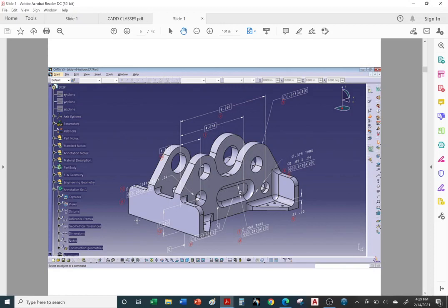The thickness of a credit card or an ID is roughly about 0.020 inches. So you're pretty much telling the machinist and the inspector it can be off by a thickness of a credit card in either direction, on the heavy side or the light side. Okay, so I would have to create a 2D drawing of a front view, top view, side views, and any additional views, and throw in the dimensions, so I can pass it on to the machine shop.